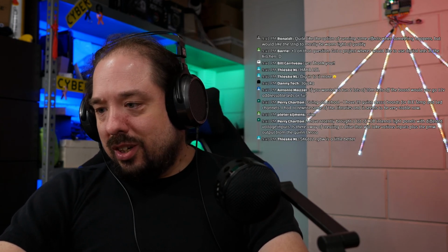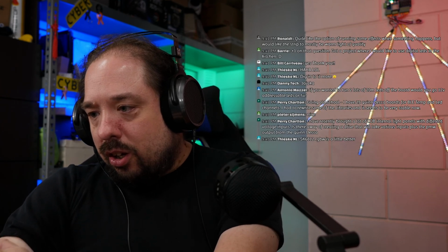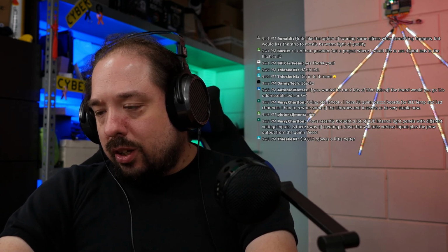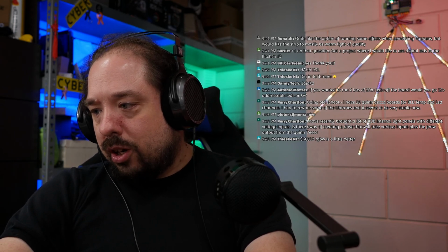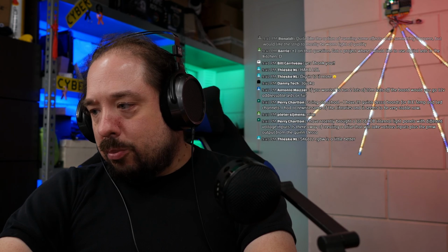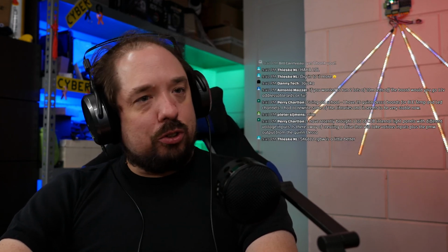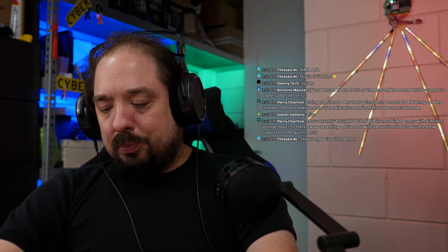That's cool. I recently bought a lot of COB internal light panels with different voltage input. Is there a way of creating a driver that will take various inputs plus the PWM output? Yeah. So I use some constant current CC COB LEDs, but if you do that, that's kind of a hack, using those on constant voltage, as you probably know.